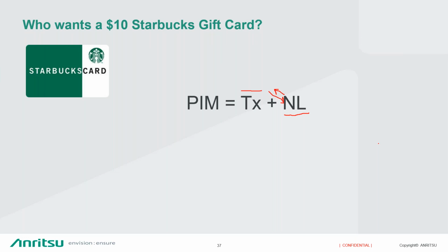If you can do that initial assessment, it certainly reduces the amount of time you have to spend at the tower. You have the right fiber and SFPs, so you can plug them into the sensor. You know that you're looking for the 700 megahertz and the 1800, for example, or whatever bands they are, and then you have at least an idea of what the tower looks like.